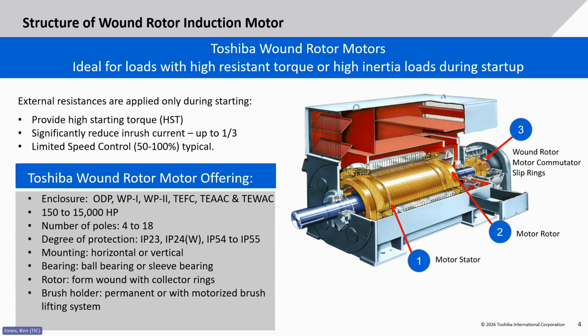As you know, typically we see with brushes a fair amount of dust that's built up within the system. We have applied, in some cases, additional blower assemblies to not only keep those units clear of dust and debris, but also allow for a longer operating life.